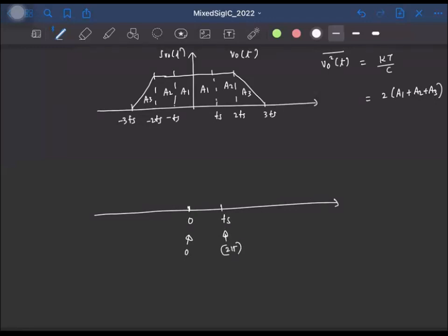Okay, and the mean squared value or the power of the sampled noise will simply be equal to the area of the power spectral density between 0 to Fs. So now we know that when we sample, the power spectral density will be repeated around multiples of Fs. So we'll have repetitions around kFs, right? So if I say for k equal to 0, we'll get back the original spectrum like this. So let me draw that first.